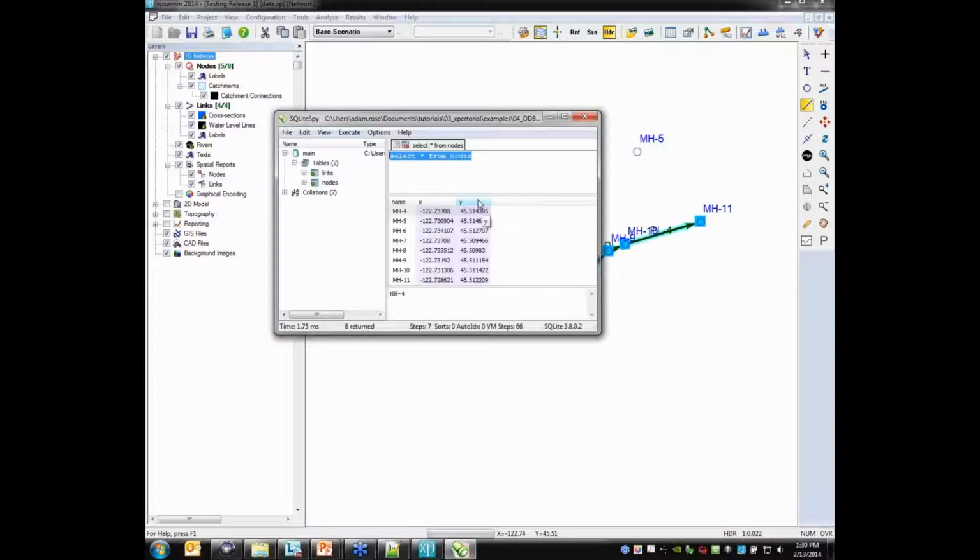This is a quite simple example, and this one is stronger on the data. You can see the X and Y field here, and it's quite easy to look at, but most spatial databases don't treat geometry as something that you can see. We don't treat it encoded that way. Typically it's encoded and stored as a binary object, which is not a lot of fun to look at through anything other than a program designed to look at it. So certainly there are GIS systems in the world that can encode that delimited text pretty much on the fly to show you points. It gets a little more complex with lines, but it's possible. But I do want to show you this example because it can be quite useful.